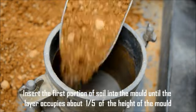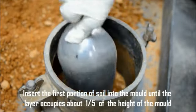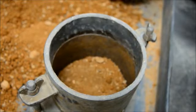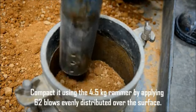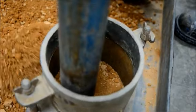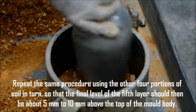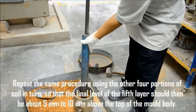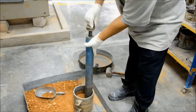Insert the first portion of soil into the mold, until the layer occupies about 1/5 of the height of the mold. Compact it using the 4.5 kg rammer, by applying 62 blows, evenly distributed over the surface. Repeat the same procedure, using the other 4 portions of soil in turn, so that the final level of the 5th layer should then be about 5 mm to 10 mm above the top of the mold body.